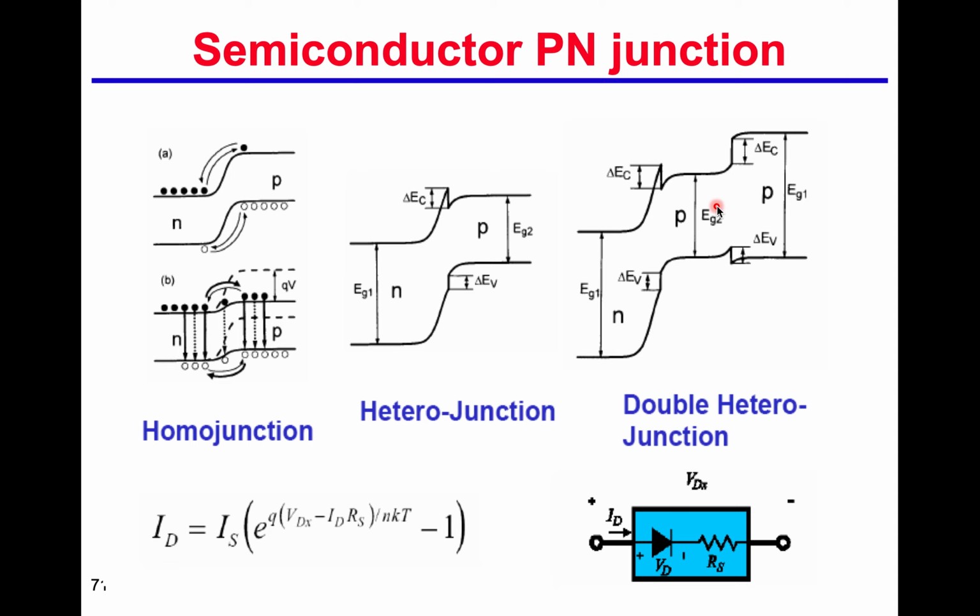And when we use the LED, the characteristic we want to use is the hole and electron recombining to generate light. So for the conventional LED, if we increase the forward bias, we reduce the barrier between the P and N type material, so the holes will go from the P type to the N type, and electrons will go from N type to P type, so they will recombine and give light.